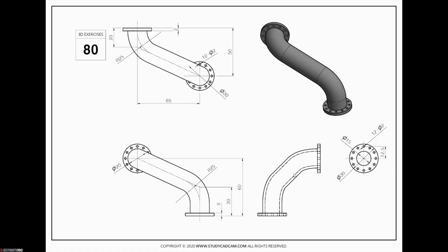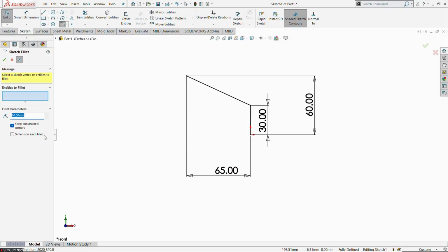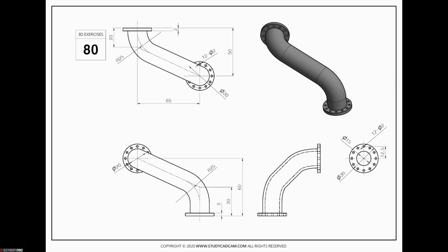Once the profile is drawn, now I am going to form a fillet at the tip of its portions. So use a fillet, initiate a radius of 25 mm and select this particular point. Pick this particular point to form a tangential formation. The front sketch is almost created.